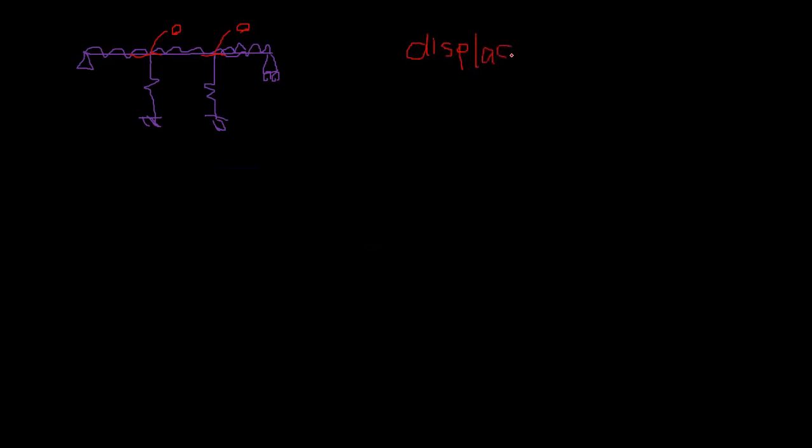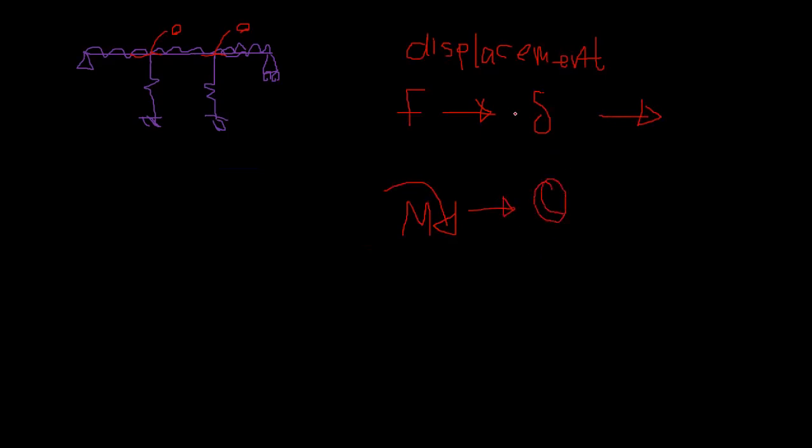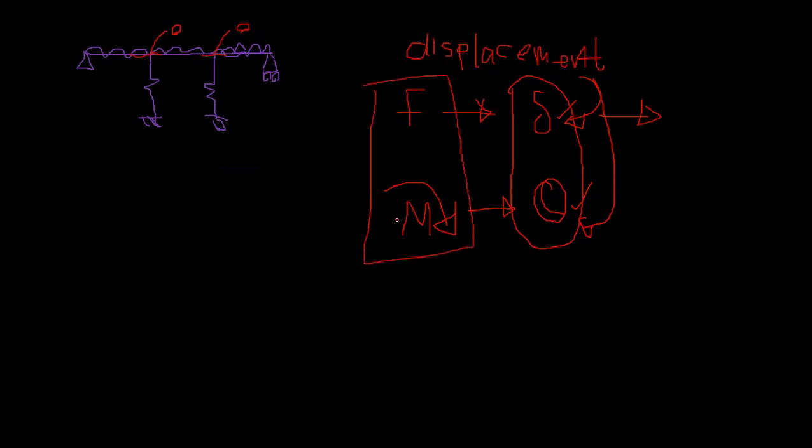So there are two kinds of displacement. Actually, a linear force corresponds to a linear displacement delta, right? In this way, a bending moment corresponds to theta, a rotation. So this is a translation, and this is a rotation. Sometimes we call this also a displacement, even though it is a rotation, right? So we use force for both moments and forces, right? It's a common term in the force method.